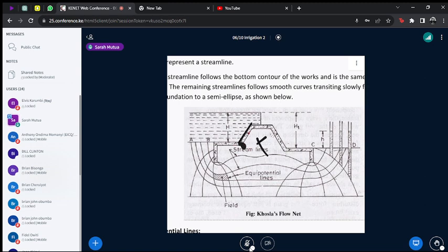If you had a pile here, you would only apply it on this particular point alone. In this case, if you had a pile here, you would also apply correction for this kind of thing. And so it can be either at the start of the slope, or at the end of the slope. For a down slope, the correction is negative, and for an upslope, the correction is positive.